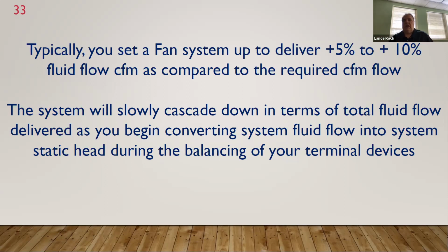And you have to speed it up anyway. We found over time, start with the system wide open, adjust your fan to equal +5 to +10% airflow, and start your balancing at that point, and you will cascade. You will slowly lose that high percentage, and you will actually proportion balance the system into itself via flow and pressure wise.